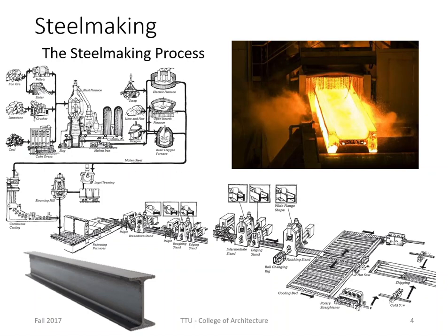So the molten steel then comes down to a continuous casting. This is made into blooms. So the molten steel is continuously cast and it is made into blooms or ingots of steel, if you want to think of it in that way. The other way is that the ingots, it's called ingot teeming, and it's sent through a blooming mill. So it may do one of these two things, but the result is that it gets into these ingots of steel called blooms.